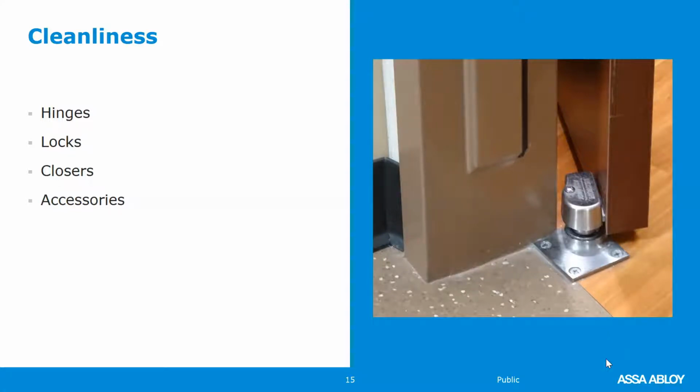Hospital stops on frames. This is a hospital stop. It makes it very easy to clean, whether you're mopping or sweeping or vacuuming or whatever. This is 4 inches, 6 inches above the finished floor. The terminated stop in this case is 45 degrees, but you could have a 90 degrees. You can still get these in fire-rated frames and use them on fire-rated openings.